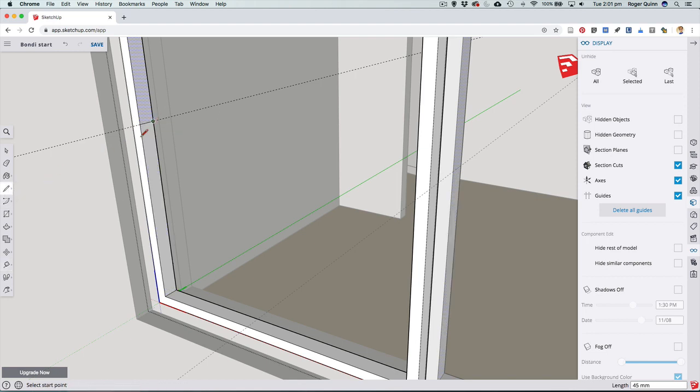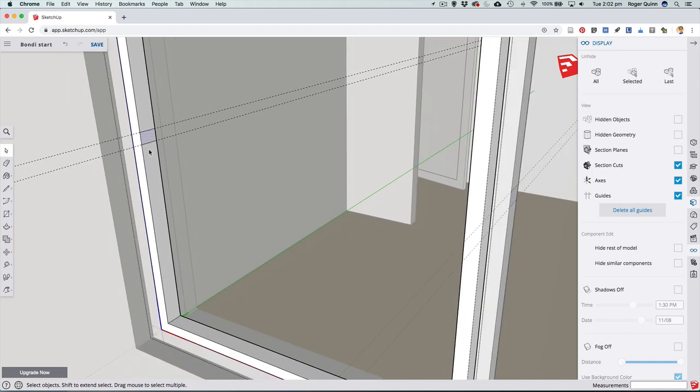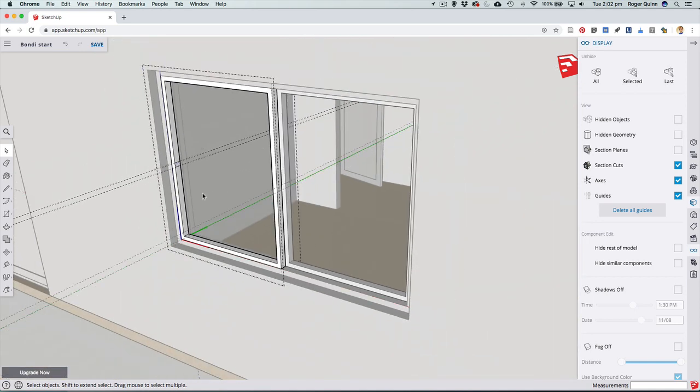Now again, just really confirming that I'm in the edit mode for this internal window. Okay. And just for consistency purposes, I'll make this also 30 deep, because that's the thickness I made these other sections. Okay, get my pencil, put a little section across there, and then that gives me a little piece in there that I can select. I'm going to push-pull that across so I get a middle strut.